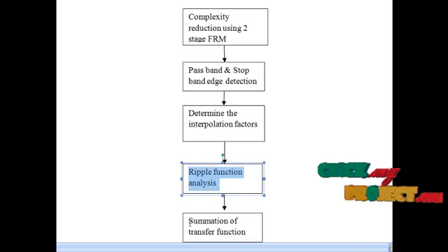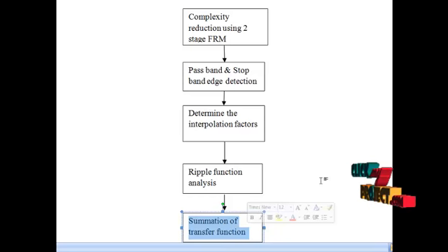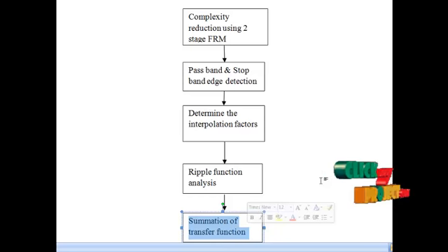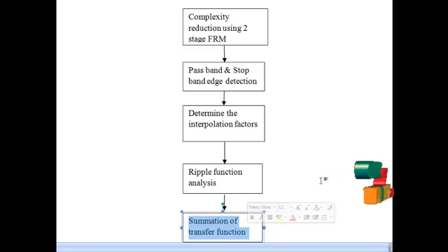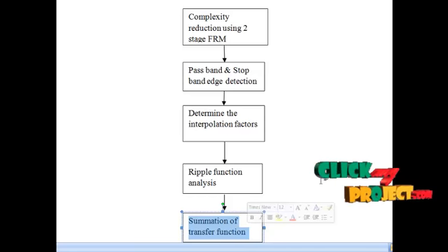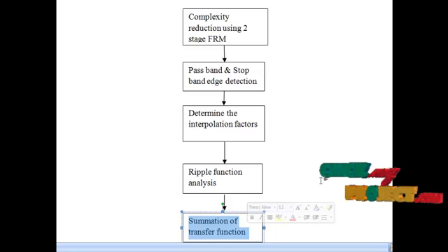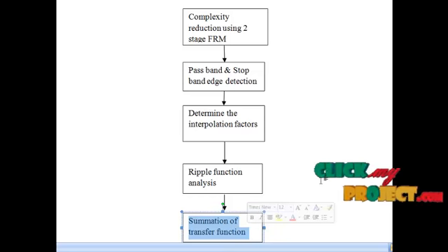The next thing is summing up of all the transfer functions. Initially there are two switches. The input signal is passed through two filters with transfer function. Then subtract the outputs of the two subfilters and store them in separate latches. That is, the output of one is kept in T1 and the other is kept in T2. The signals in the two latches are passed through a filter with transfer function. This is added altogether to get the final output signal.